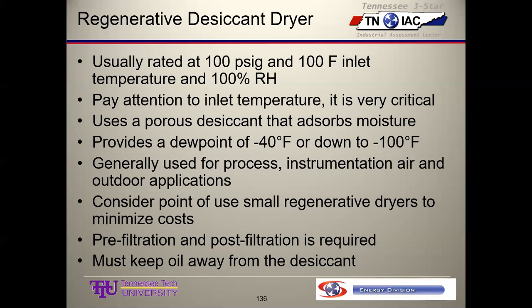These desiccants use a porous desiccant bead, and these beads are different materials. I can't remember them off the top of my head. There's a bunch of them, but they have lots of little cracks and crevices, and the water molecules stick. It's not any sort of a solution, and there's no chemical reaction. They simply stick to the desiccant bead. And after a while, all those cracks and crevices get saturated because we got all the water molecules hanging off there that will fit. And so then the desiccant has to be regenerated, which means you have to do something to drive off all that water that's stuck to the beads, so then you can go back and dry again.